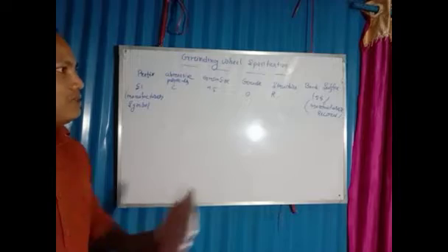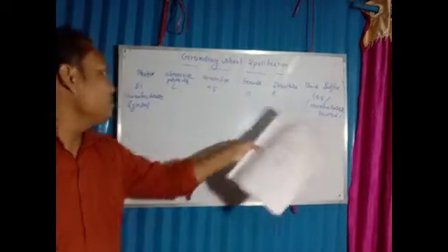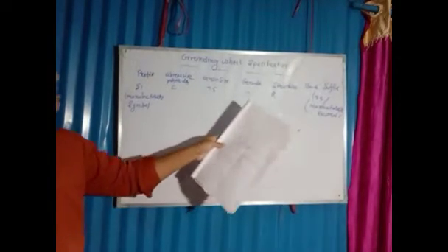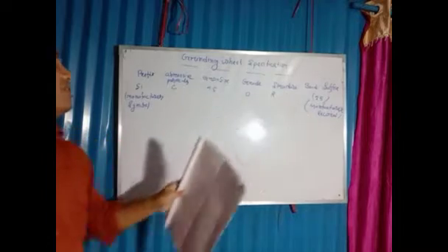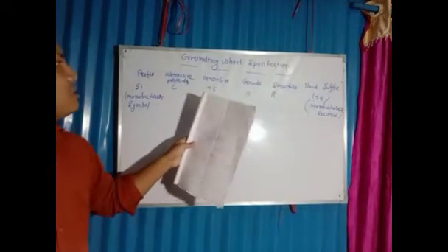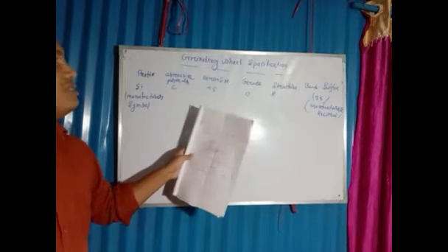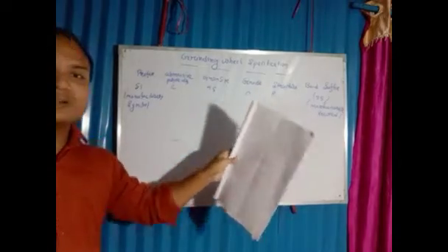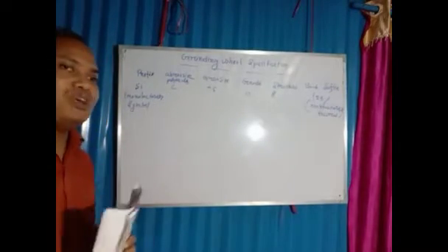So prefix and suffix are not important. You have to first focus on the abrasive particles, grain size, grade, structure and bond. What abrasive particles are used, what the grain size is, what the grade is, what the structure is, and also what the bond or bonding material is.